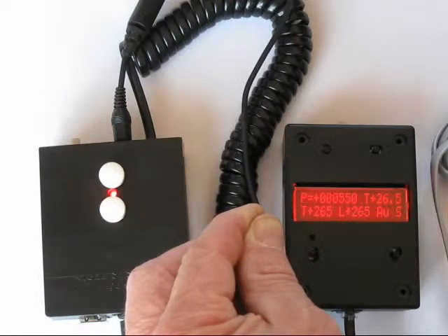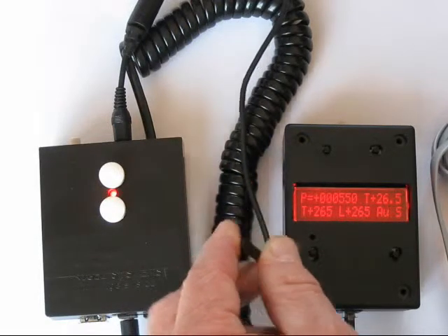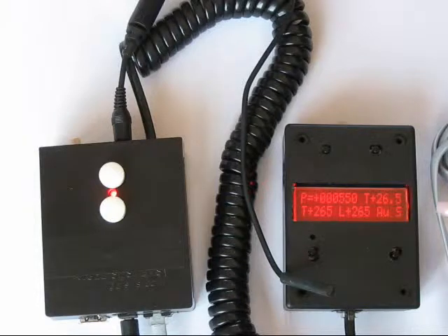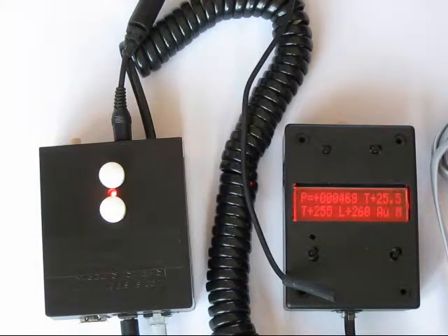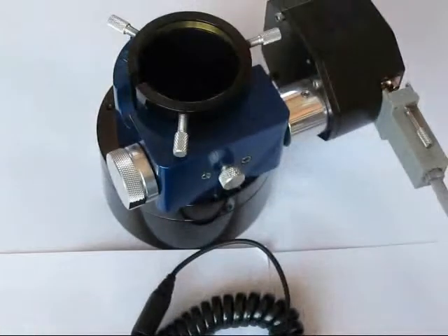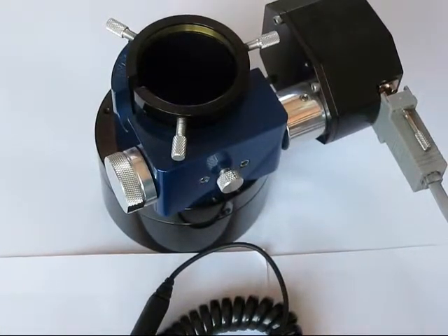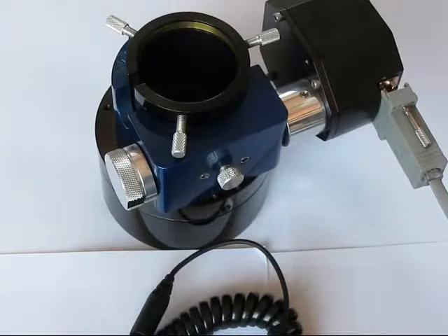Okay, now I'm going to let go of the temperature sensor, and it should start walking backwards. You should see this go to B for a short period of time as it takes up the backlash compensation as we reverse direction, and it starts moving. Okay, and we can see it, so this is moving at 50 steps every half degree C change.